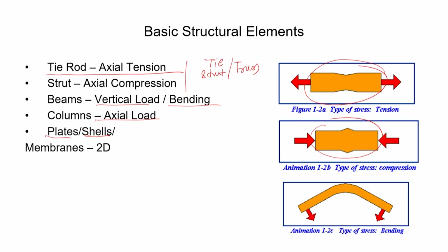In the form of shells, even thinner shells can still carry some bending moment, but membranes cannot. Membranes can only carry distributed tensile forces. So these plates, shells, membranes, etc., you can call the thin shell structures.